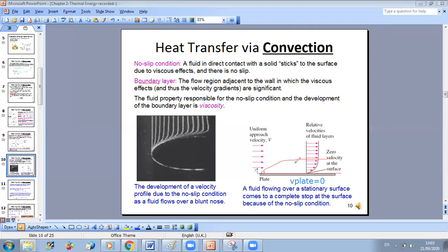Because outside of your boundary layer, you have uniform velocity. So everywhere outside of the boundary layer, you have uniform velocity equal to big V. While inside your boundary layer, you have variation of velocity from 0. So velocity is starting at 0, and then it's increasing until reaching V. So at each level of your plate, you will have a small zone, which is a transient region, where the velocity is varying from 0 to V.